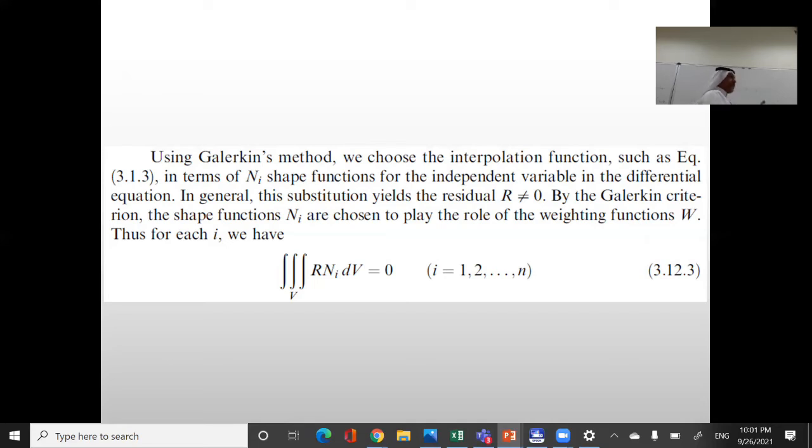And T is coming from what? From stress. T is equal to sigma times the area, right? And stress is coming from strain. Strain is du dx, times E times A. So what if I say T equal to constant? What is dT dx?